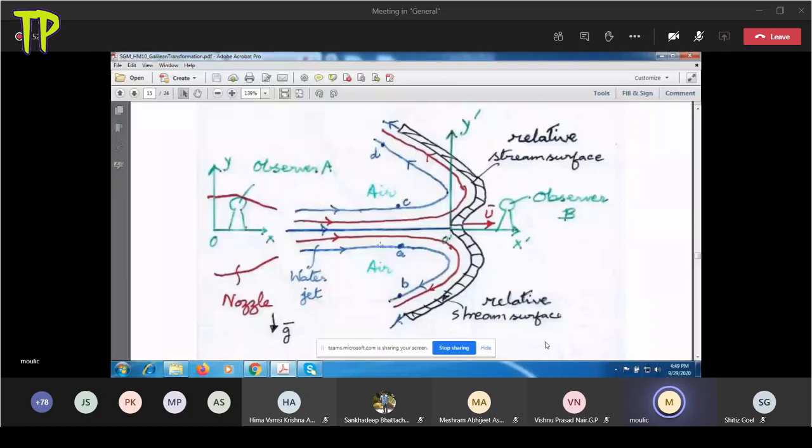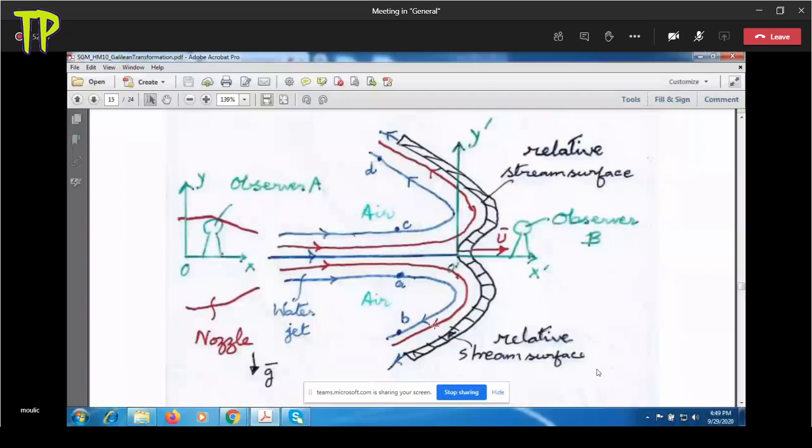So when the vane is not moving, the velocity at B and the velocity at A will be the same, assuming that viscous effects are negligible. Very good. So now I think you are beginning to understand things. But even if the flow is inviscid, if the vane starts to move here, then the velocity at B may not be the same as the velocity at A.